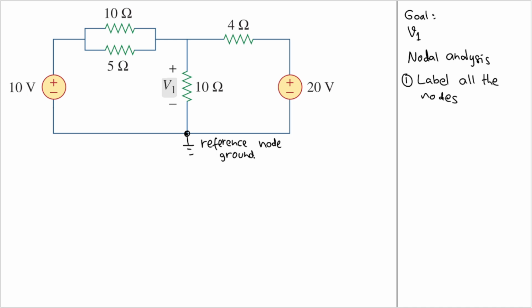And what does that mean? That means that the voltage here will be 0. Good. But if this is 0, we can also get this node here, right? Why? Because it is connected by the 10-volt voltage source. And remember, the voltage source is the difference between its positive terminal and its negative terminal. But its negative terminal is 0 here. So we can infer that this node is 10 volts from the ground, because 10 minus 0 is 10.